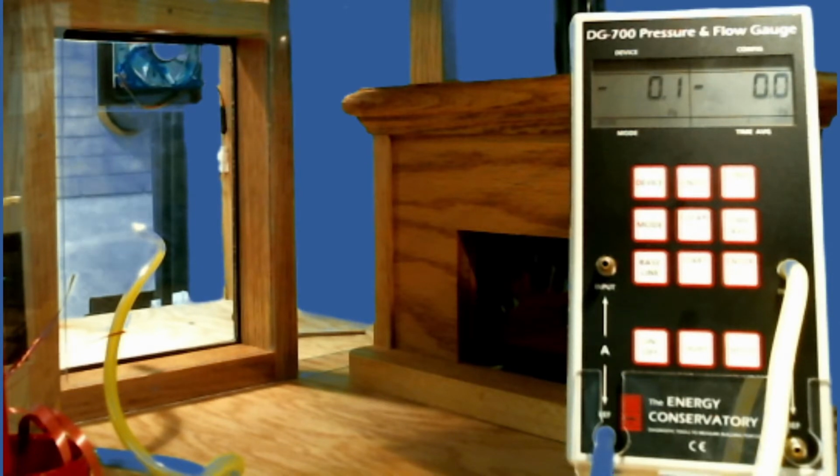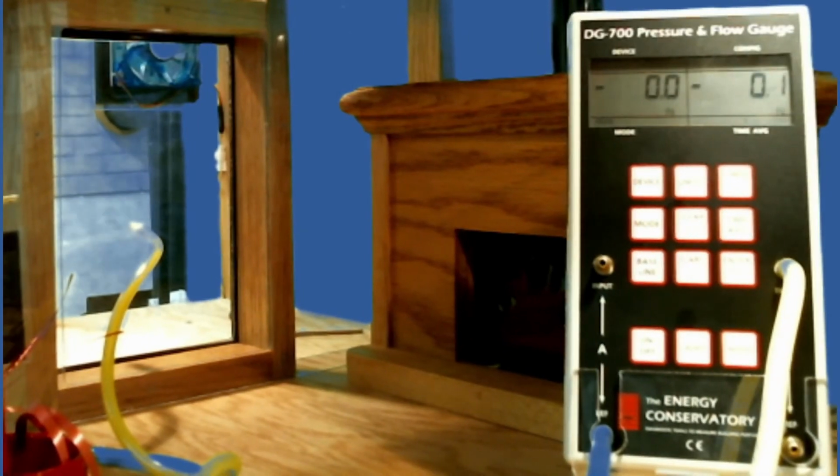So what we're going to do is turn on the air handler fan. I'm going to put the window back on. The air handler fan is off at this point, and then I'm going to turn on the furnace fan, and we'll see what that number on the right will be, which is the pressure between the room and the house. And like we said, the left will be the house and the outdoors. So I'm going to turn it on and see what happens.